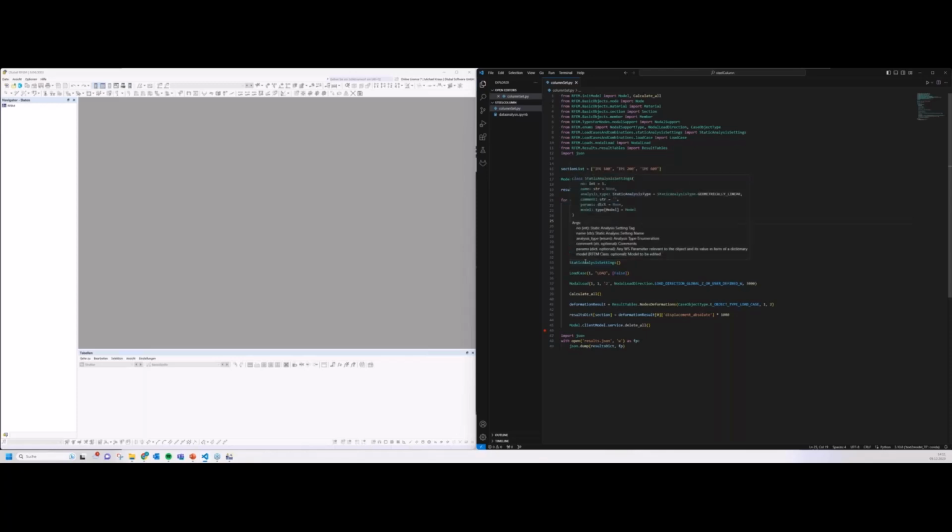Then we can jump right into the load case definition. Here we define a load case 1. We exclude self-weight, and then we put a nodal force onto the second node in the direction of global Z with 3 kilonewtons. Then we execute the computation and save the results from the RFEM computation, delete the model, and go into the next counter.